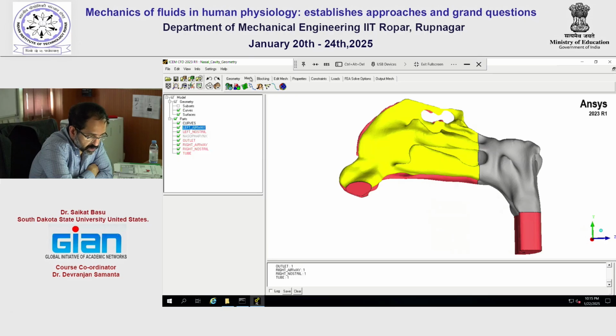In other words, you are tracking the particle deposits along the walls. So next to the wall, the mesh has to be finely refined beyond what is there in the basic tetrahedral mesh. To do that, we will do a second layer of grid resolution where we develop prismatic cells along the walls. But that is the second phase of meshing. Let's first try to get the tetrahedral mesh built.